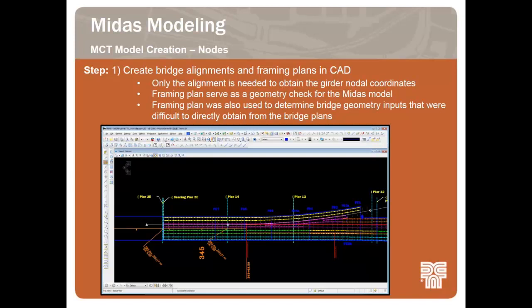and the offset distance to a girder is not to the center line of the girder, which are used for modeling, but to the exterior flange, and the top flange openings typically can vary along at any given span, which makes it very difficult to try to do it by hand, and can also make it more complicated to try to do it with Excel equations with a more black box approach.